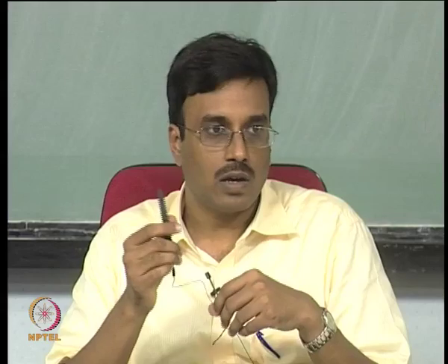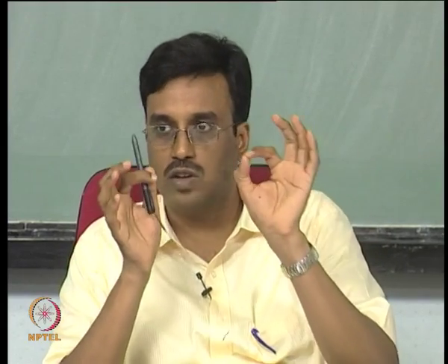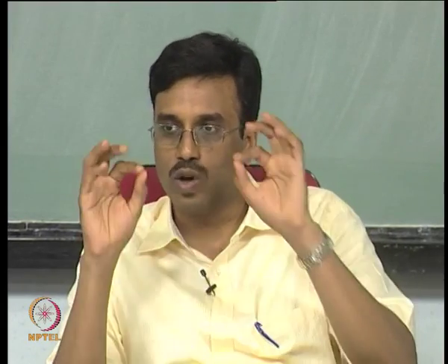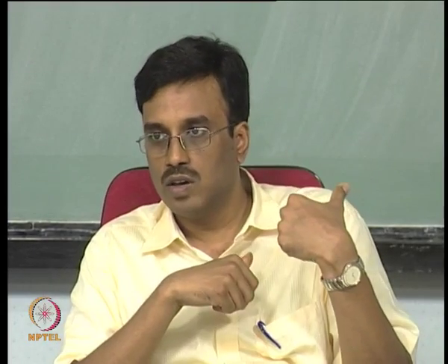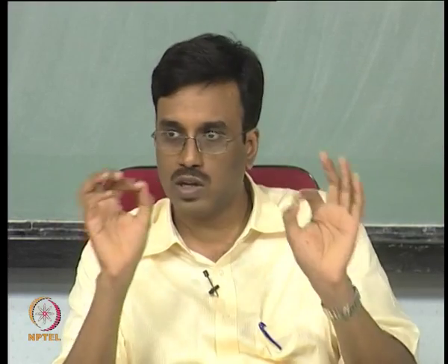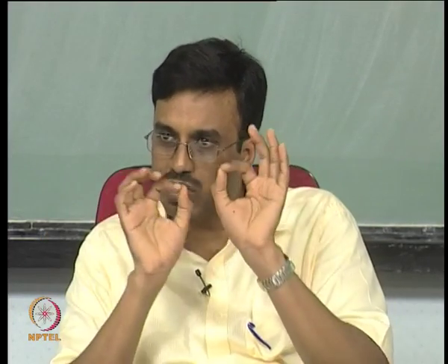How it is going to be used, we can figure out later, because you have these two ends. You can now think of this as a capacitor with some voltage across it. Now this voltage is a good reproduction of the voltage you wanted to sample. What you do with this floating capacitor is up to you. In fact, this is exactly what you want: a capacitor with both terminals accessible, with the voltage you want on the capacitor.